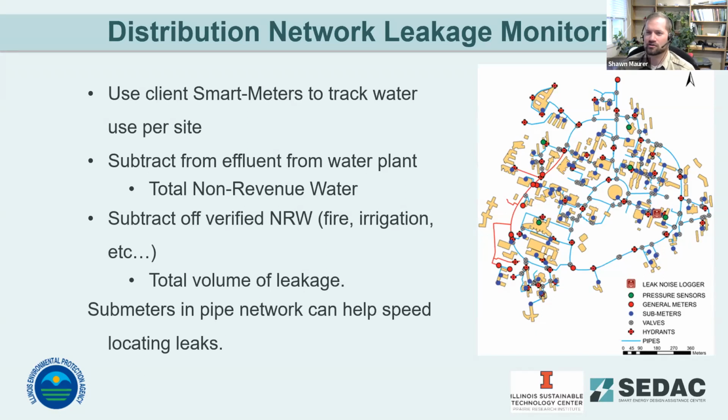If you've got a really large municipal district with multiple control zones, pressure management can help even out the pressure across all those control zones and make sure that everyone's got similar pressure requirements, that someone's not drawing down and causing low pressure somewhere else in your network. And so again, high topographic variation is going to give you the most benefit from having pressure management systems, but that's not the only place that it's applicable. There are other times when you can use that.